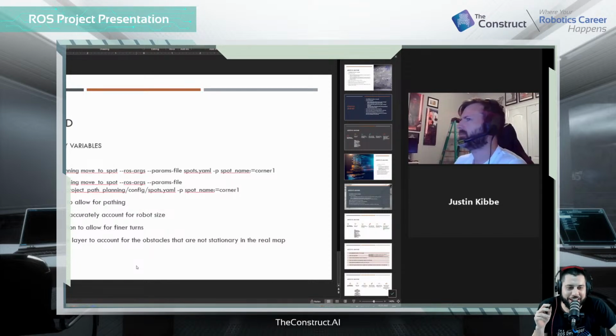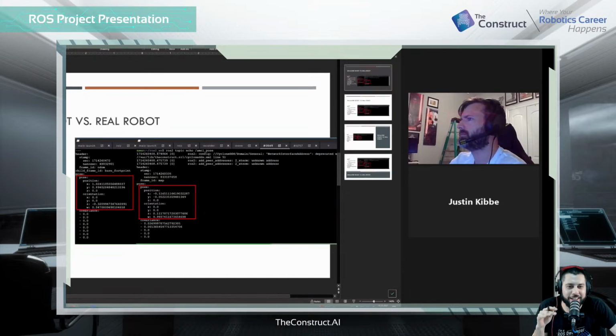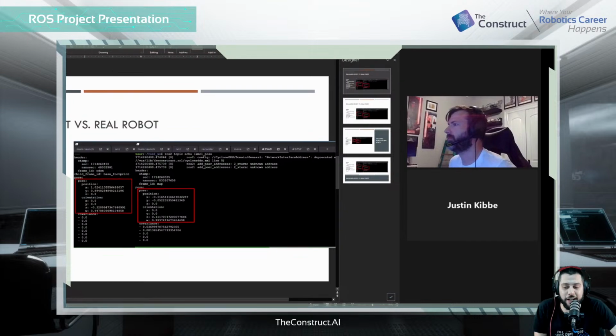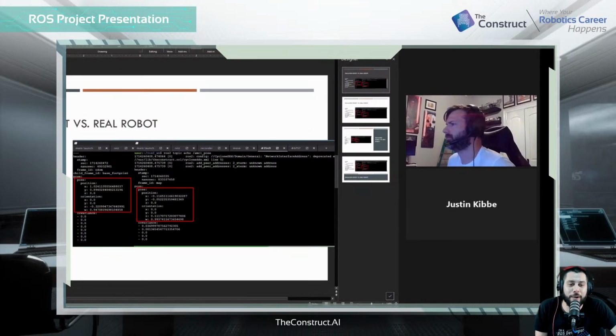So I forgot. Could you go up in your slides? Yes, this one exactly, the AMCL versus odometry issue, which is confusing. The reason why odometry wouldn't work was basically because of two things. When you start the simulation, the odom topic is always going to be 0,0,0, because that's a plugin from Gazebo and you just start it up, unless you change it for whatever reason.